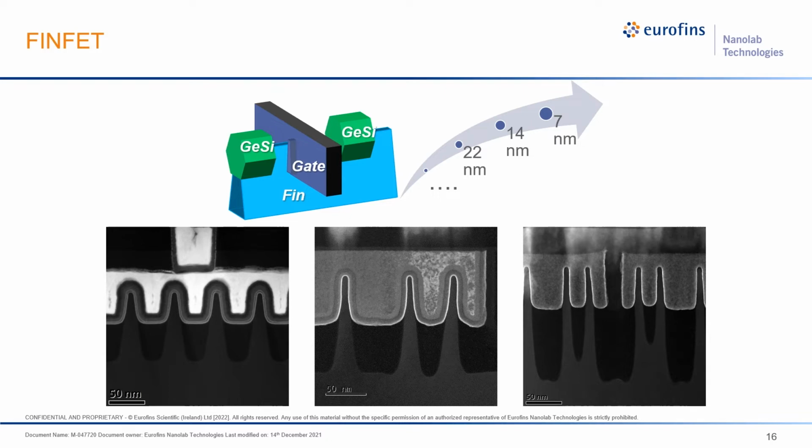So as technology advanced, the dimension of the FinFET keeps going smaller and smaller. So this increases the technology complexity in process development. In the process development, there are a couple of important parameters to measure, such as critical dimensions, CD, the fin height, fin width, pitch distance, etc.